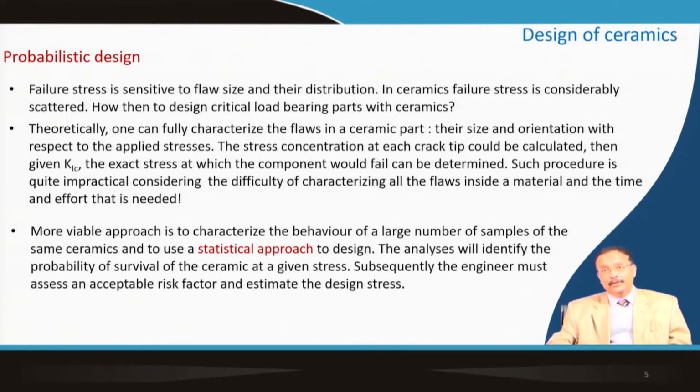It is possible at least theoretically to characterize the flaw size in the ceramic part. In each individual ceramic, what is their flaw size, what is their orientation with respect to the applied stress. The stress concentration at each crack tip can be calculated, then you know the fracture toughness, you can measure the fracture toughness.